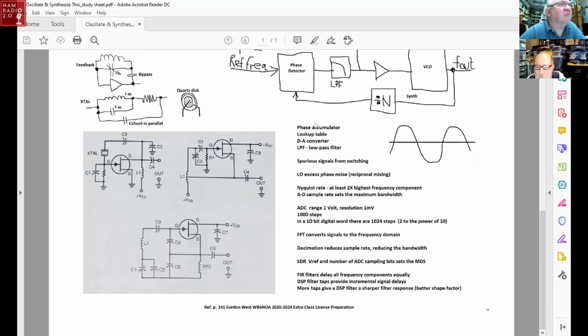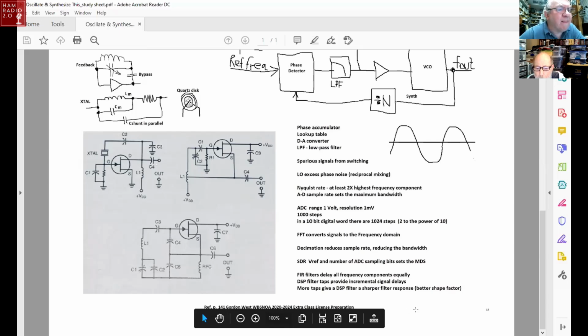The other problem with this diagram is that the power supply voltage, instead of being shown at the top, comes down to the bottom with L3. And it would be clearer if that line went up instead of down. Okay, let me switch to another view of this. Yeah, the orientation on the drawing is really bad. They tried to adjust it, and you know, orientation is not always clear on schematics.